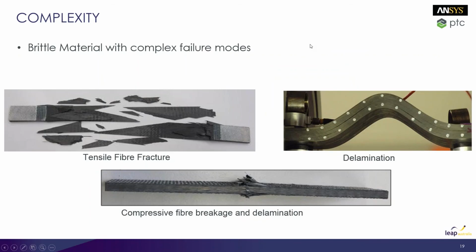The other really complicated thing about composites is that, because they're made up of different materials, their failure modes are very, very complicated. This is only exacerbated by the fact that most composites are quite brittle. They won't display much or any plastic deformation before they go. So if we were loading our fibers, and our fibers are fracturing under a tensile type loading, we get quite a dramatic, kind of explosive effect when the specimen will break.